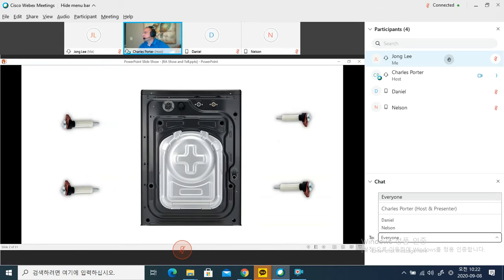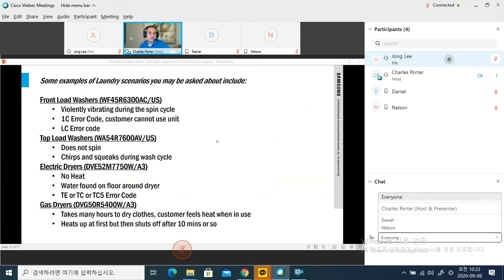All right, so after you check for your shipping bolts, you'll want to go ahead and check and make sure the unit is level. Check the floor and make sure that the floor itself isn't too pitched or too unlevel where you're not going to be able to level the unit.